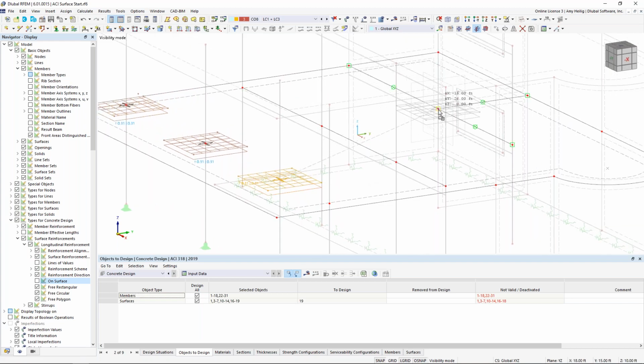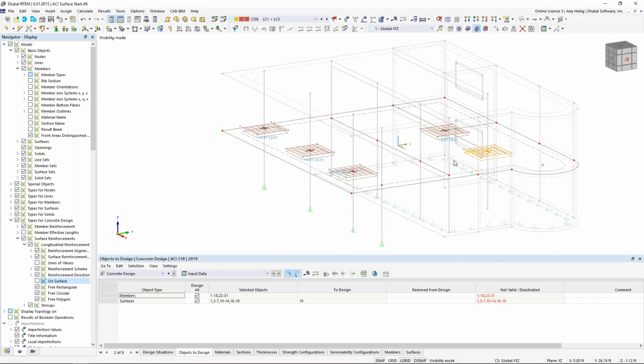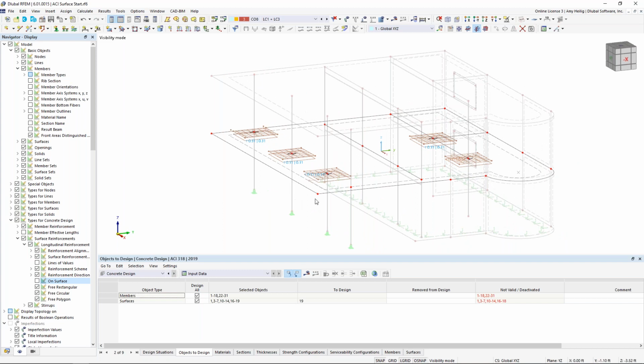I also have some areas back here where we kind of intersect with the walls and columns that need a little bit more reinforcement on the top. So of course, we'd want to continue optimizing this best we can based on the internal forces. Again, we probably want to add some shear reinforcement and such to the slab. Now, just taking you to another little side note here, punching shear, this will be ready actually, hopefully in several weeks for the ACI. It wasn't quite ready for this presentation, so we're not checking that right now, but that should be very close to being done within the program.